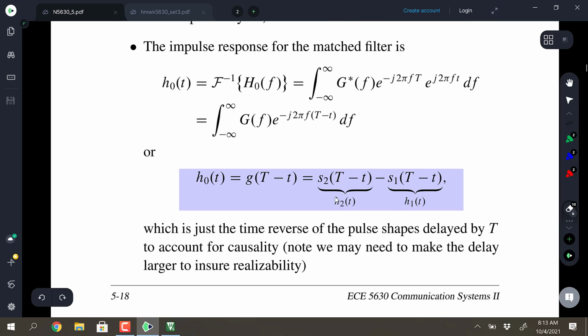And again, going back to what I was saying a moment ago, if the signal passes through a filter like this, and S1 is orthogonal to S2, so an S1 goes through and gets convolved with this H naught impulse response, the second term is going to give some large output because it resonates with it, whereas S2 is going to get ignored if S1 and S2 are orthogonal pulse shapes, and then vice versa. So that all works out nicely.